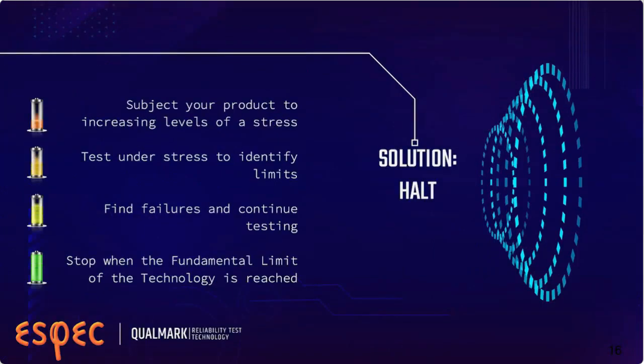Now here you see the main building blocks of a HALT test. From the beginning, we talk about subjecting your product to increasing levels of a stress. One of the key words here is increasing levels. We're increasing the stresses in a stepwise fashion, dwelling at each level and doing functional tests at each level. So we're not necessarily hitting it with just great big hammers. We're hitting it with progressively larger hammers so that the very weakest things fail first. We learn what the true weak links are in the product.